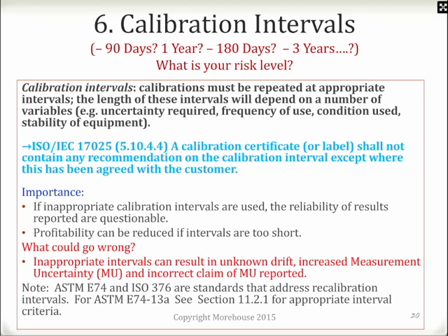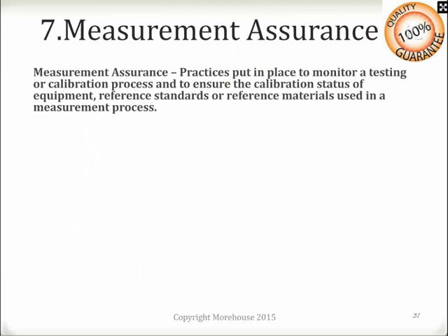That basically says for Class A devices, over the calibration range, the percent change has to be less than 0.16%. And for Class AA devices, the change has to be less than 0.032%. If that criteria is being met, a 2-year recalibration interval for that standard can be applied.